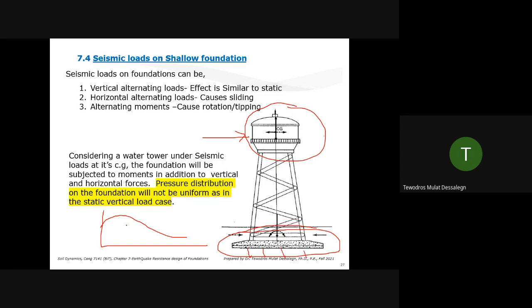But we were studying there to see how you pick accelerations, how you compute period of that structure. The period of this structure may not be easy. Simplified equations from Roark's formula, you may not find it for something complicated like this. Simply regular shapes, rectangular shapes, circular shapes, or hollow, you may find that one easily. But something like this, you may have to use software to model it. If you model this in software, in SAP or STAAD.Pro, you can find what fundamental period it has.